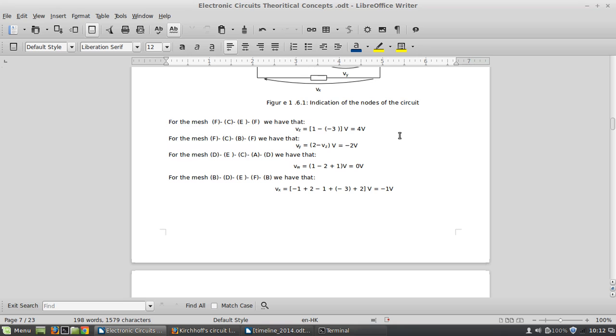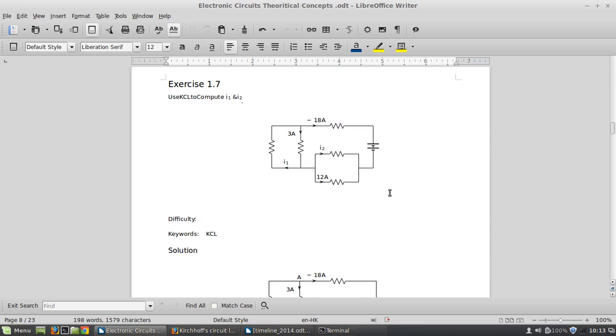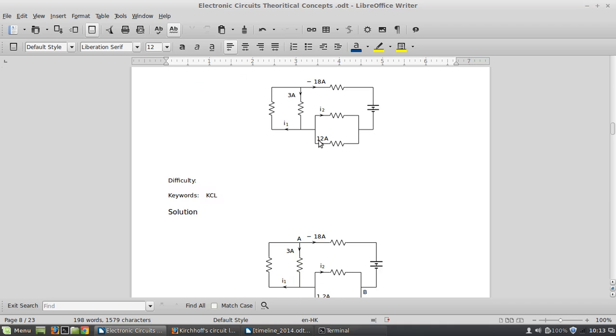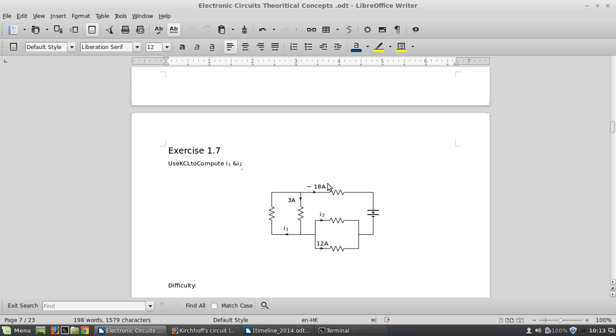After finding VZ, you go through this second loop and find VY. So at this point you have found VW, secondly you find VZ, and thirdly you find VY. After knowing VY, you find VX, going through this particular loop. Alright, so loop 1, loop 2, loop 3, and this one is loop 4. And that's it, a simple addition and subtraction.